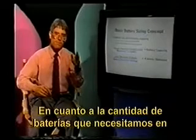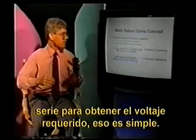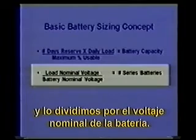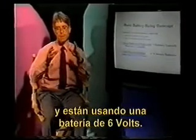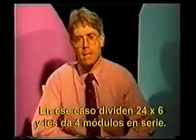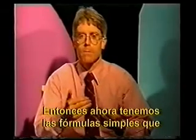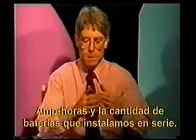In terms of the number of batteries we need in series to give us the voltage that we need, that's fairly simple. You take the load nominal voltage, the system voltage, and divide that by the battery nominal voltage. For example, you might be designing a 24-volt system and be using a 6-volt battery. In that case, you divide 24 by 6 and end up with 4 modules in series. So we now have the simple formulas that we need for calculating battery capacity in amp hours and the number of batteries that we install in series.